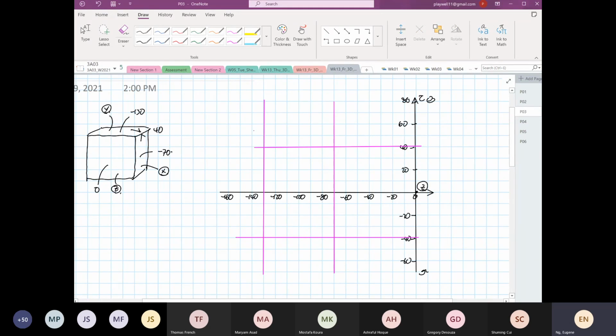So this is my point X at the minus 70 line, right? It's going anti-clockwise. So this is my point X. And over here, this is my point Y, okay? So from here, I'm eyeballing this. The center of the circle is still here, right? There is your O. So to get the radius: 20, 20, 30, so 40. So 40 squared plus 30 squared, the square root is equal to 50. So this circle has radius 50.